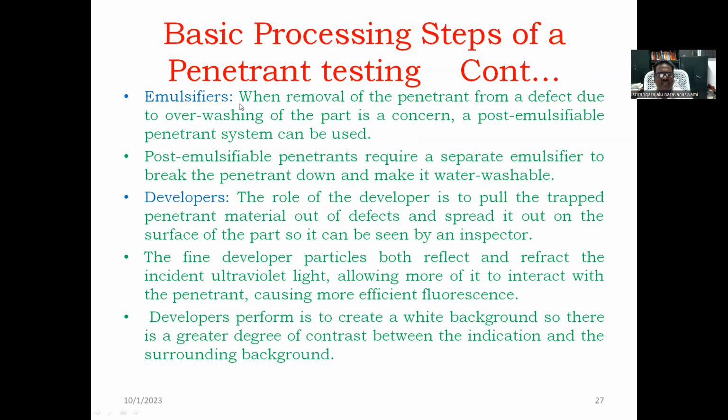The emulsifier: when removal of the penetrant from the defect due to overwashing of a part is a concern, a post-emulsifiable penetrant system can be used. Post-emulsifiable penetrants require a separate emulsifier to break the penetrant down and make it water washable.